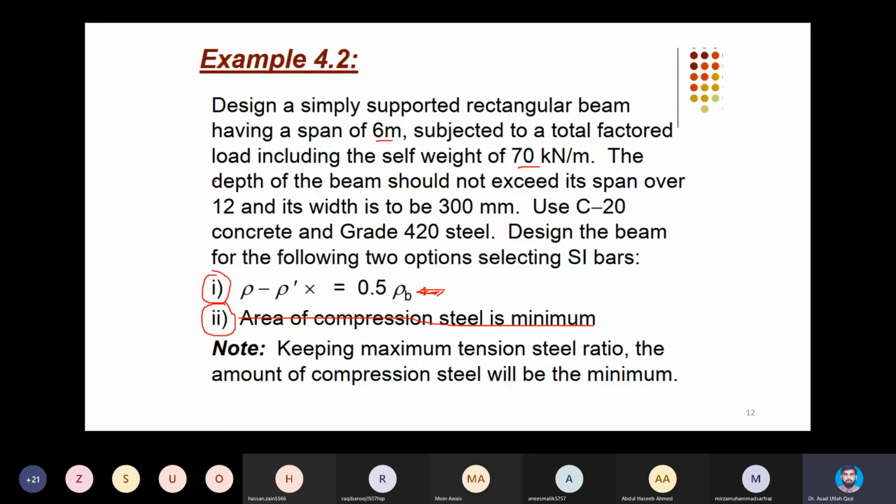Obviously, you can discuss with the architect regarding some spacing of the columns. You might have your concerns if spans are large, but finally, you will have to get to the values. You obviously will ask the architect about the floor finish thicknesses, type of floor finish, type of building, so as to select appropriate live loads, structural use. But finally, the drawings and other information with cross sections will be provided to you with some architectural restrictions, and then finally you will get to such spans and loads.